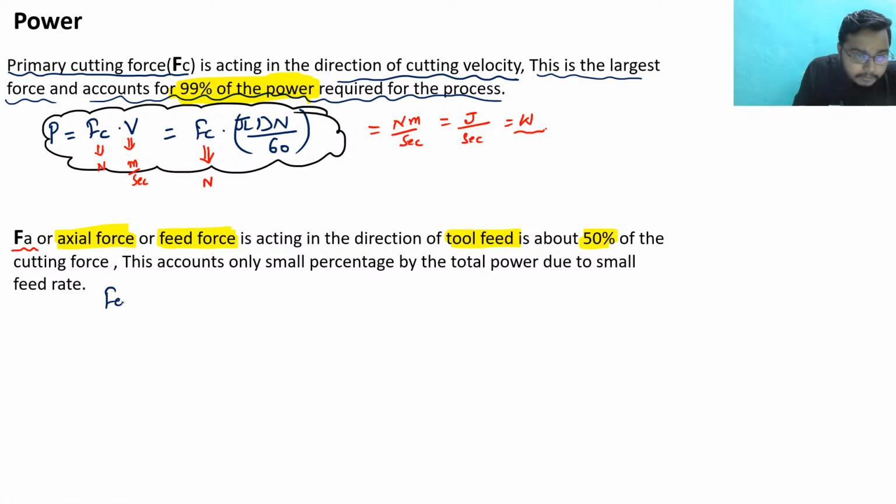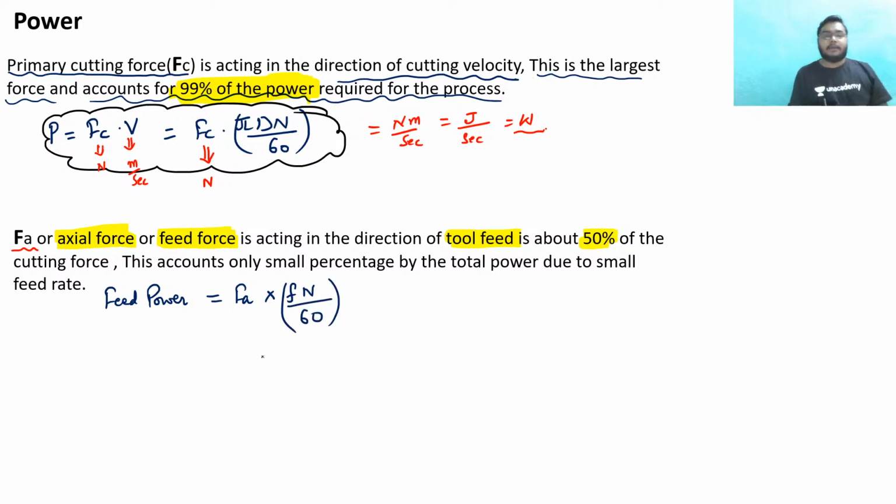So feed power is nothing but axial force into F N by 60. Sir, this axial force is also known as feed force. Okay, so do not confuse with that.